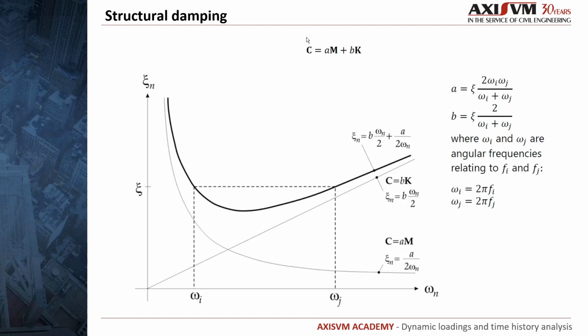There are many formulations for the damping matrix, but the most often used and most easily programmable is the mass and stiffness matrix proportional Rayleigh damping. The Rayleigh damping coefficients control the proportion of the mass and stiffness matrix, and they should be calculated from the damped frequency range and the damping ratio according to this figure. Since it is a two-parameter description of the damping, care should be taken choosing the relevant frequencies.